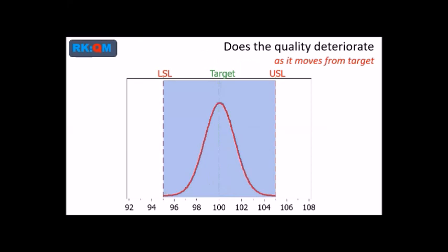We try to manage our process so that we produce precise quality product. But so often we have a variable process like this. Within a delivery, we find a distribution of dimensions, as shown here, in decreasing amounts as the dimension moves from the target.